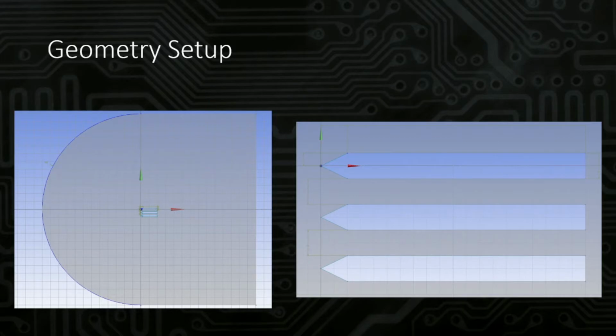So here's the geometry that we made. This is about a 1:5 scale to an actual pontoon boat. Each one of these pontoons is exactly 1 meter long. They are each 0.1 meters across, and they are each 0.1 meters apart. And the reason we scaled this down is because of processing power. If we made it the actual size of a pontoon boat, it would have taken way too long to generate.